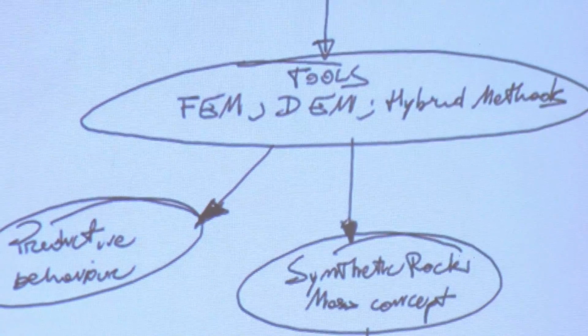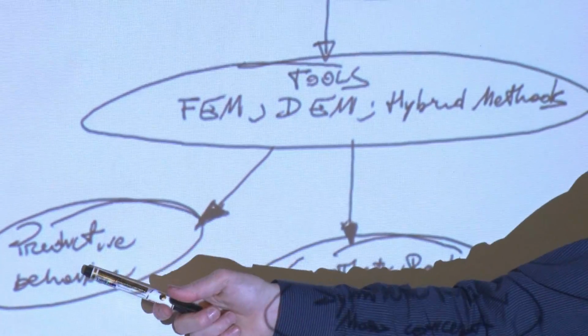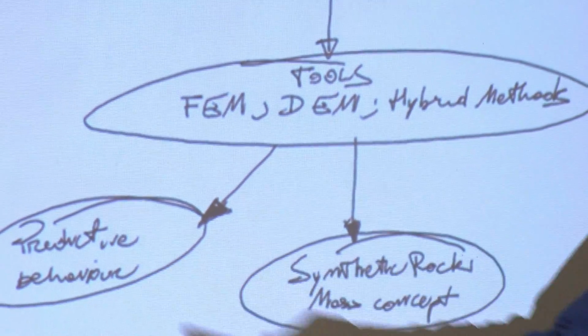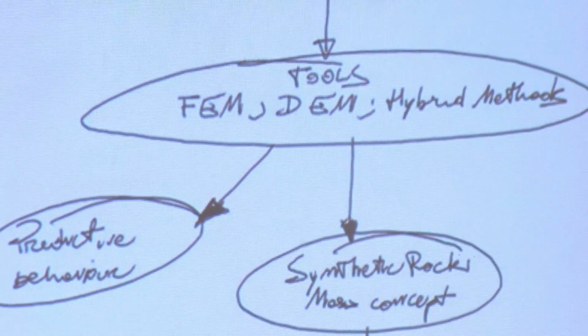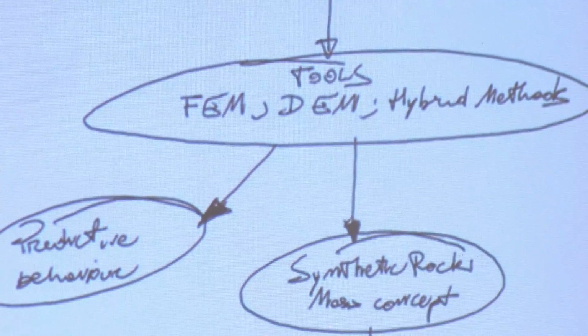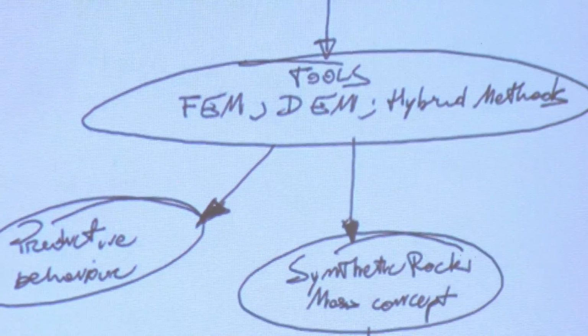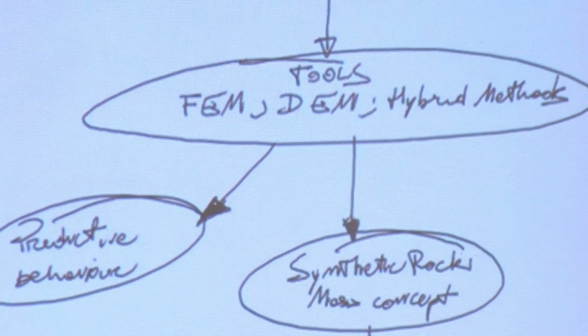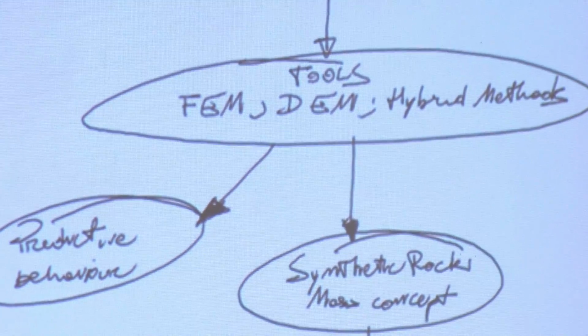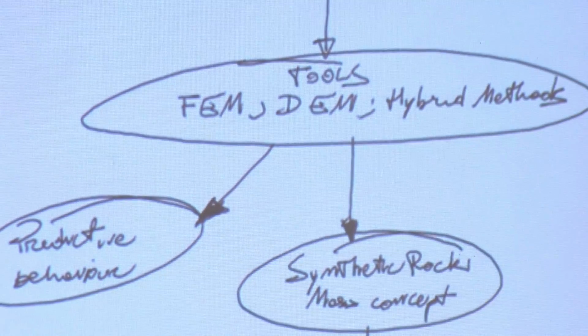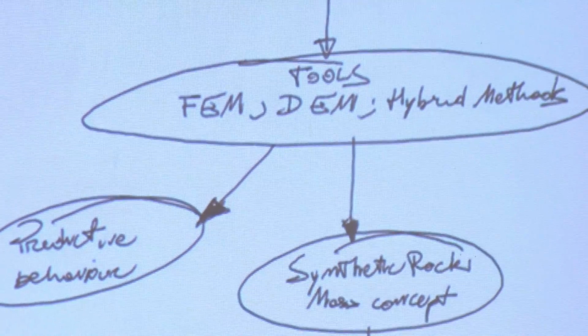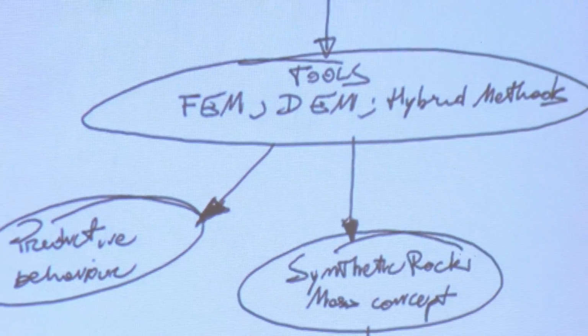And what you are going to try to use them, you need to calibrate. It means that you need to assign the parameters. You assign the parameters by looking at laboratory tests. For example, if you're using a Mohr-Coulomb criterion, you're looking for the cohesion and the friction angle. And you can measure those in the lab.